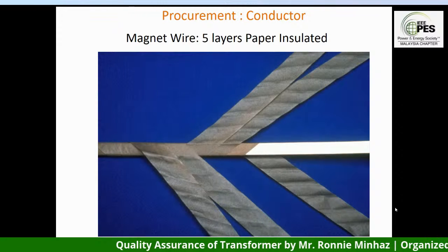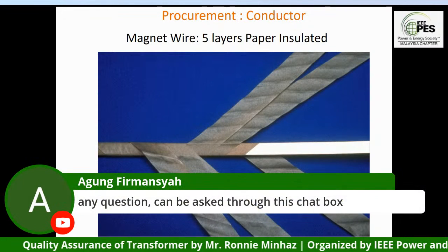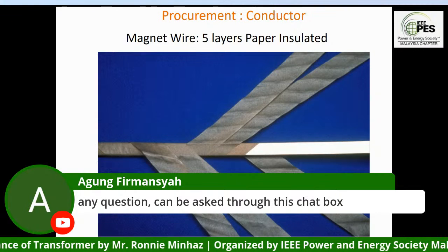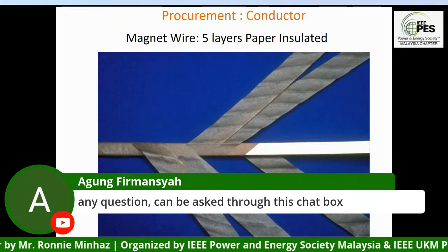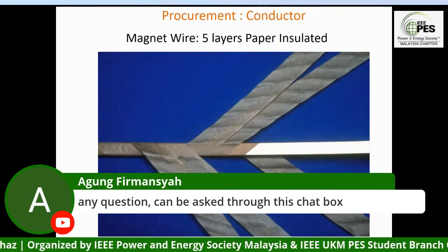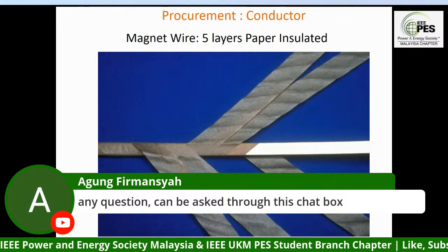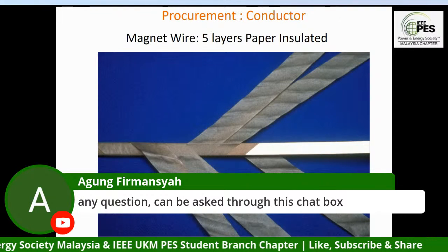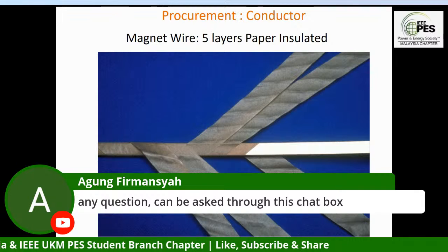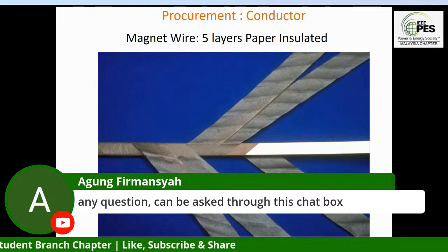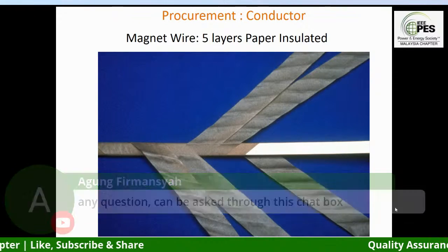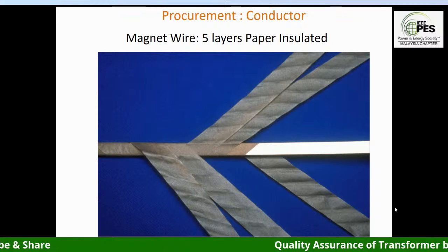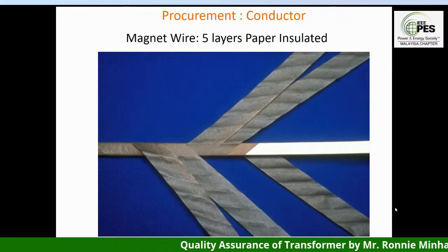And there is no way you can pick it up by factory acceptance test. So what is going to happen, this reduction of 20 millimeter within 5 years is going to put a stress into the quality of the transformer. Now, not only that, when he reduced the insulation to 40 millimeter, he said that in this 40 millimeter, I will give you 5 layers. You can see in this picture right now, 1, 2, 3, 4, 5 layers.